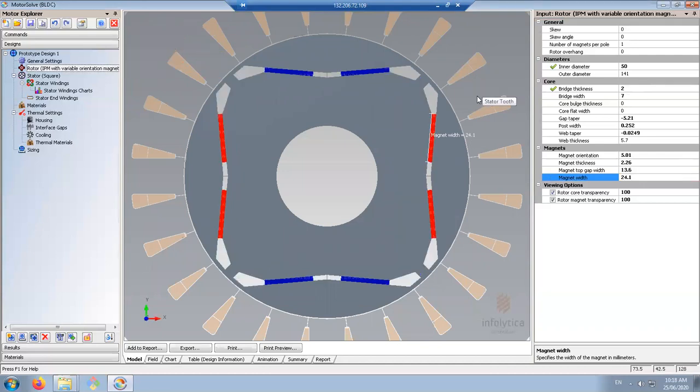However, I would suggest that you always, during your optimization process, because once you want to do optimization, you have to use MATLAB or Python or VB to automate this parameter changing, right? To call MotorSolve, automatically change the parameters and everything, not manually like what I'm doing here, right? Because you need to do this for several thousands of samples.